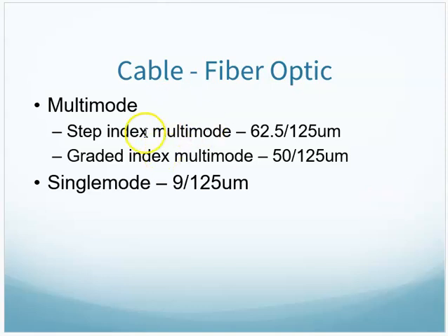And then there's the sizes. There's your step index 62.5, 125, graded index 50, 125, and single mode 9 to 125. You notice the outside, the cladding, is standard among all of them.